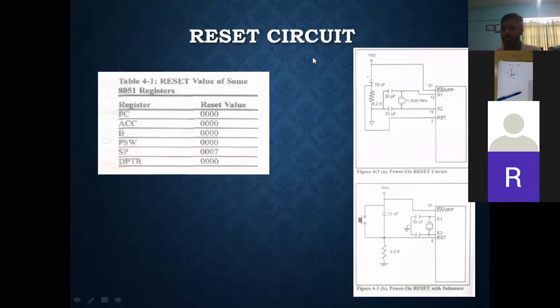Can you remember what is there at address 07H in the 8051 microcontroller? We discussed it in the earlier class. Bank register. Right, very good. So 07 is the R7 register of bank 0.